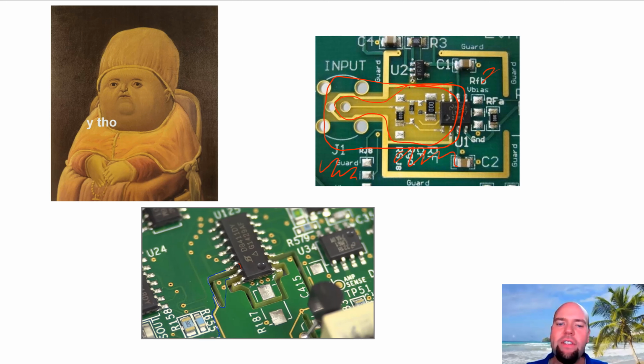Even if it's just 1,000th of your signal, that's going to be noticeable. So to avoid that, a lot of times we don't want to have big resistances. So we do tricks like the T network to avoid these undesirable phenomena that result from us swimming in gig ohm resistances. If you really want to go crazy, you can literally cut holes in your circuit board.